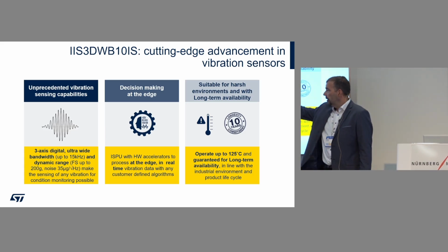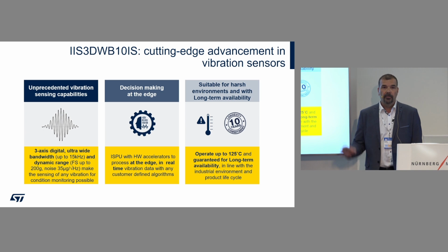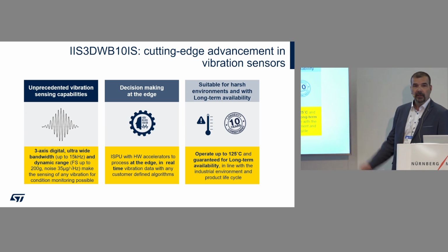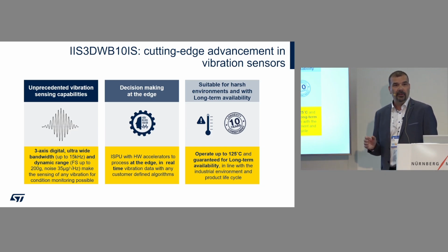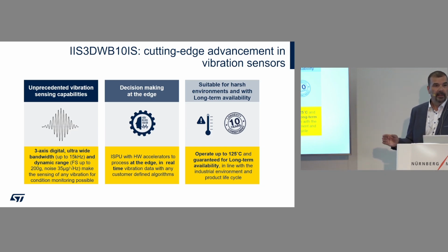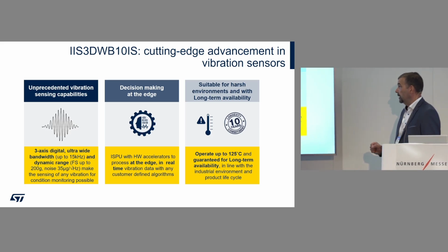a very important point is that on top of the vibration sensor itself, we are also integrating a RISC core. So you can program your own algorithms in the sensor. For example, you decide to program an FFT inside the sensor. So you want to calculate on the fly the frequency spectrum in the sensor, you can do it. And you are just getting out the results of the FFT.